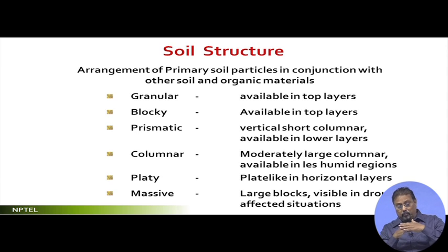Since it is platy, if there is creeping of water within, the individual plates are being held with in-between components, and those components are not strong enough to hold each other because water has crept in and made it almost like a lubricant. Then the micaceous particles start dissolving into the water, and at this intersection point it becomes a very dissolved, sticky lubricant. In such a case the plates slide against each other, and once the plate is sliding, the stability is gone. So structure matters a lot.